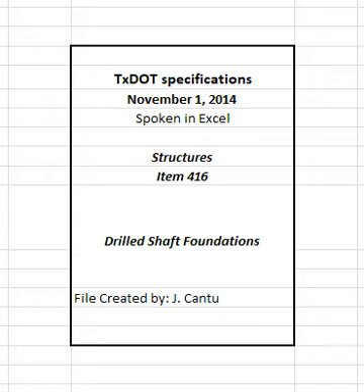Use coarse aggregate grade 4, 5, or 6 for drilled shaft concrete in reinforced drilled shafts. Grade 2 or 3 may be used if the shaft is dry and reinforcing steel has a 5 inches minimum clear spacing. Use a water-reducing, retarding admixture in accordance with DMS 4640, chemical admixtures for concrete, in all concrete when using casing that will be pulled or when placing shafts underwater